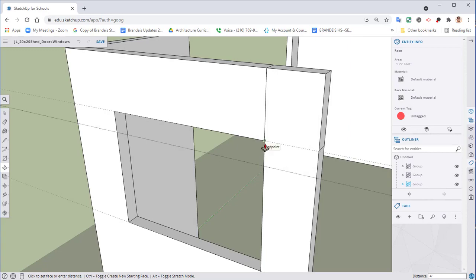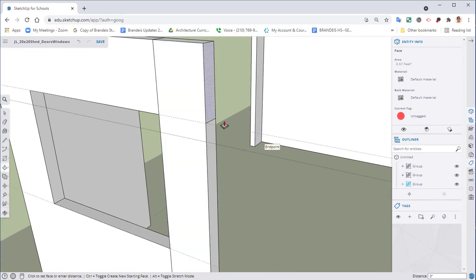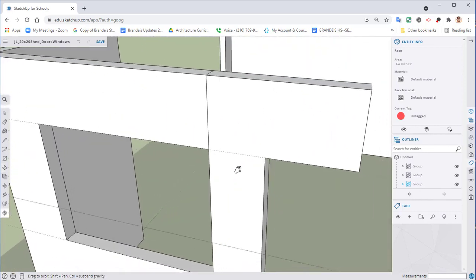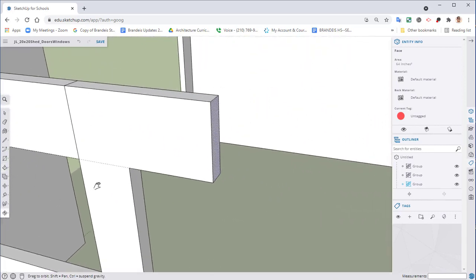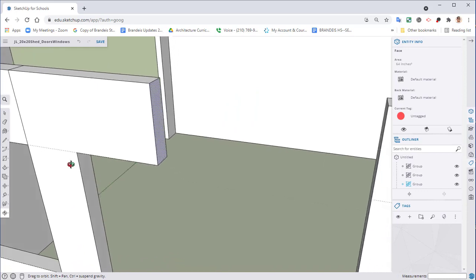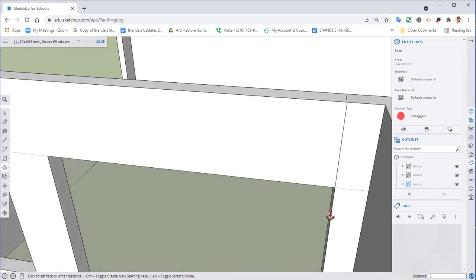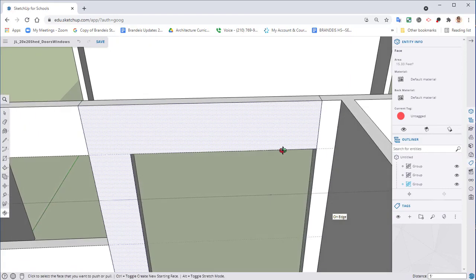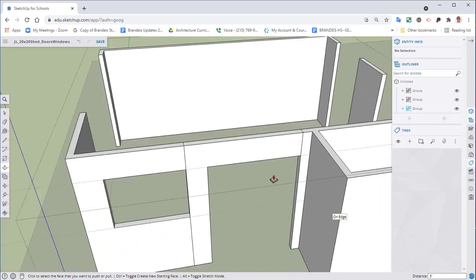We're going to just inference that edge and pull over the door using our keyboard shortcuts of the middle scroll wheel and the shift key in order to bring this over. If you don't use any kind of shortcuts at all, that's the one you want to use: your middle scroll wheel and your shift key in order to rotate and pan your project around, and the scroll wheel using the zoom keys.